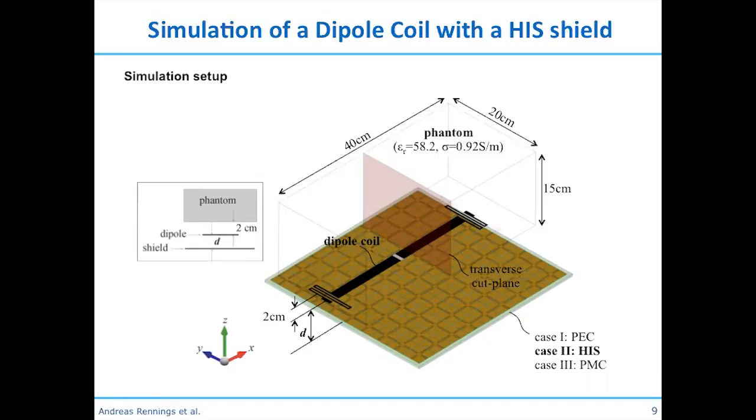Final comment, we added around the meander a high dielectric substrate to fine-tune this electrical length a little bit, to fine-tune the current distribution along that dipole. So it's essentially an ordinary dipole, but the section where you have the low current, where it's going down to 0, that section is meandered because it's not really useful in the MRI context. There we need the strong and quiet current